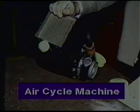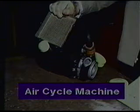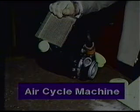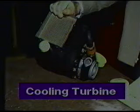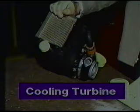The air cycle machine converts high-pressure engine bleed air into low-pressure cold air. The unit may be separated into two principal components, the cooling turbine and the heat exchanger. The term cooling turbine is often used to refer to the entire assembly.